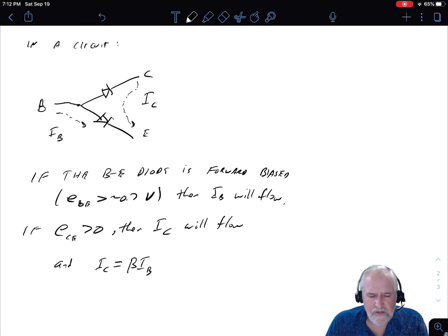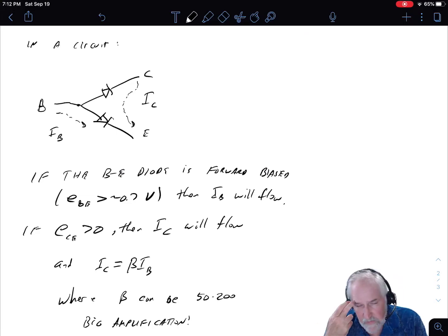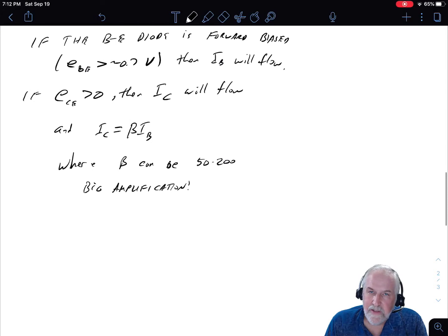These transistors tend to have two different kinds of modes. We call them saturated and linear. In the linear mode, that collector current will be directly proportional to the base current by some constant beta, and beta is a large number, 10 to 150 to 200 maybe. So 100 is not an unusual value for the transistor constant, and that's really useful, as you can imagine, for amplification. So if you're catching this tiny little signal on an antenna from a radio transmission, and we want to amplify it, send it into the base, it creates a larger current.